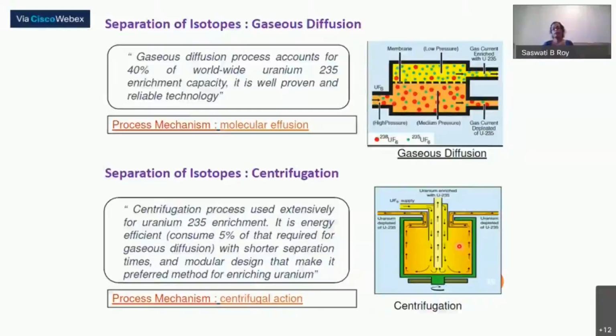In combination, we have made a circuit where the depleted stream comes out here, and the enriched one comes to this center tube. A very difficult pressure balance is needed there. First of all, it has to be totally evacuated at the initial level, and only then can you put your UF6. And this is called one separation unit.